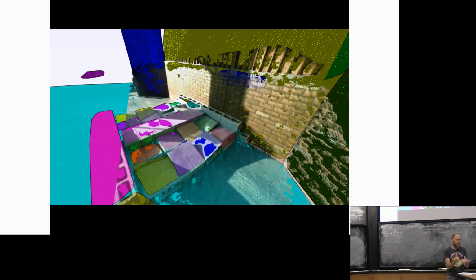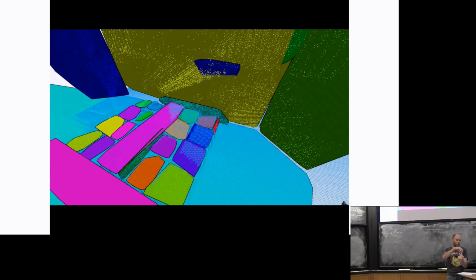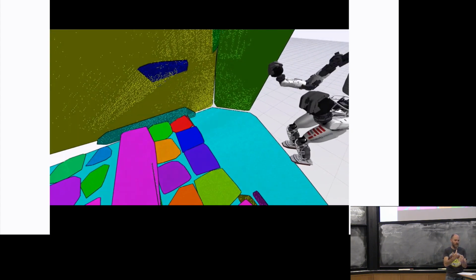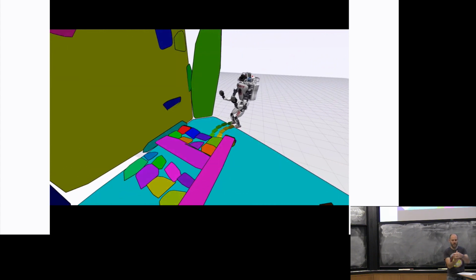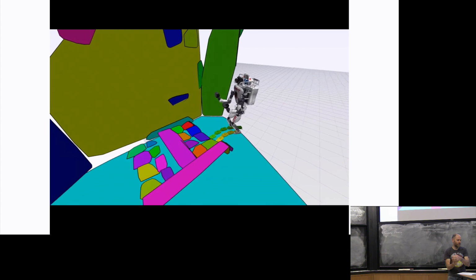That was a reasonable thing to expect out of your perception system, even at the time: that using the depth cameras, you could image the world and compute the normals at every point by doing a local plane fitting approximation, and then group points that have similar normals into regions that are flat, regions where you could potentially step.